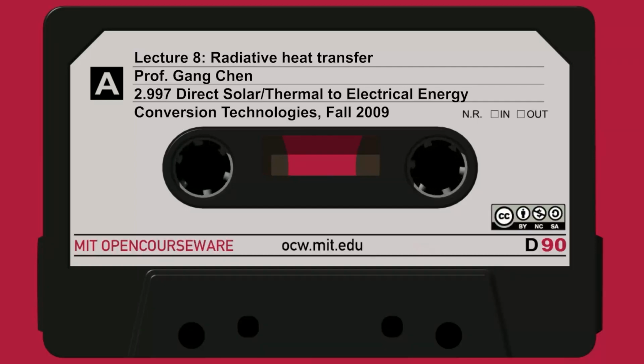So with this definition, I still think there is a pi, but I'll check that. So I have pi r squared, cosine theta i, cosine theta j, dAj. That's for a different small area. The two surfaces are small. Does anybody remember this pi? If I integrate over both surfaces, I get the total, if the surface is uniform. And so that's the view factor.